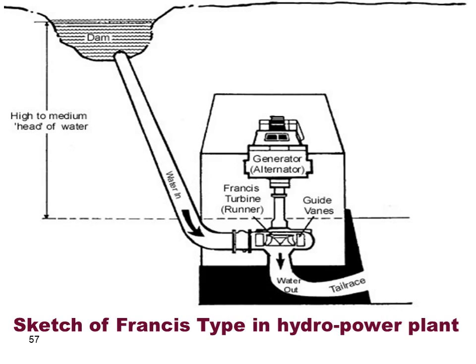This high water level can be drawn to the turbine through a pipeline or through a tunnel, we call it penstock, then to the casing, and inside the casing you can see the runner and the guide vanes around the runner, and then after the turbine it goes to the tail race or downstream through a draft tube.